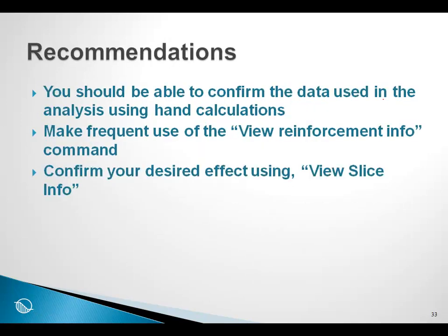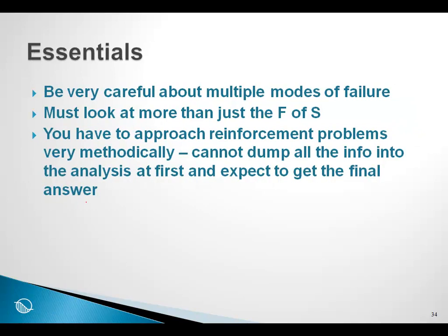We recommend that you confirm the data using hand calculations. Throughout these presentations on reinforcement, we have done a lot of spot checks with hand calculations. You should be comfortable doing this in order to use the reinforcement in SLOPE/W. And as we have done throughout this presentation, make frequent use of the View Reinforcement Info command and confirm your desired effect using View Slice Info, as we have done in all of these examples. We cannot overemphasize the importance of doing this as part of the interpretation of the results.